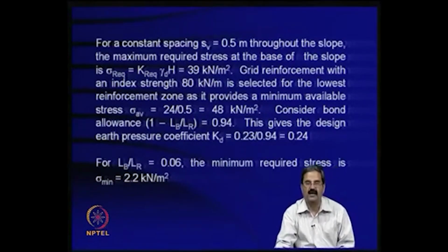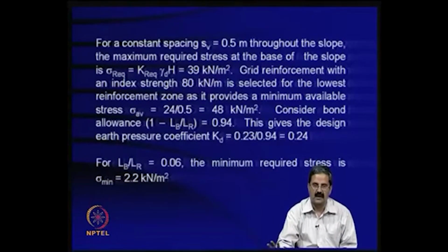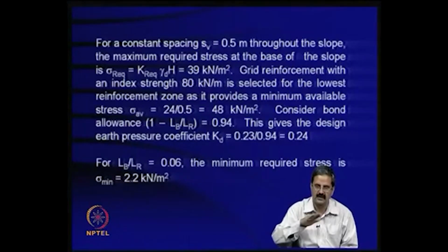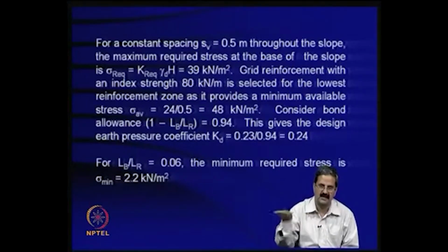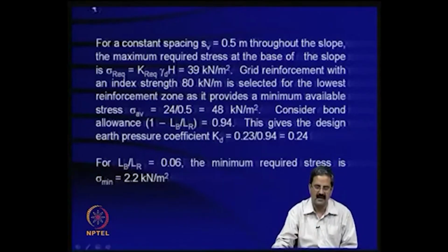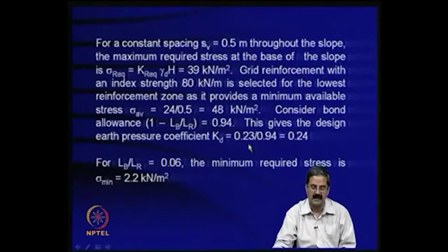For tension, the reinforcement should be placed in the direction of tensile strains for maximum benefit, and for the bond it should be placed at 90 degrees to the vertical stress. But in the field condition there is an intermediate angle, because of which the K required has to be corrected, it has to be increased actually.